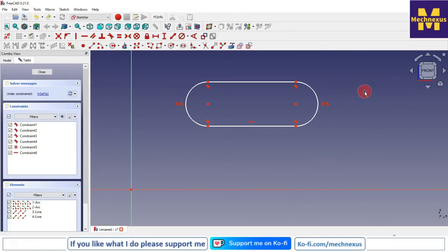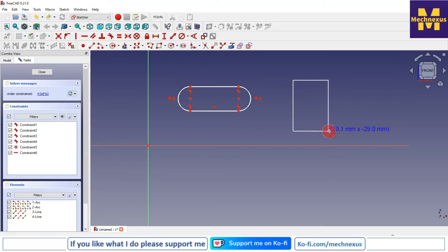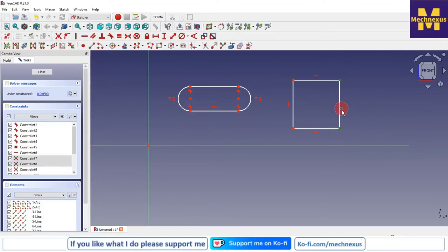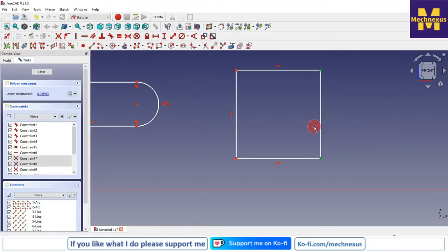For example, if you want to manually select for a line or arc, if I select this line and click on this, the associated constraint of this line, the tangent, got selected. Similarly, if I create a rectangle and select this line and click on this icon, the vertical constraint got selected.